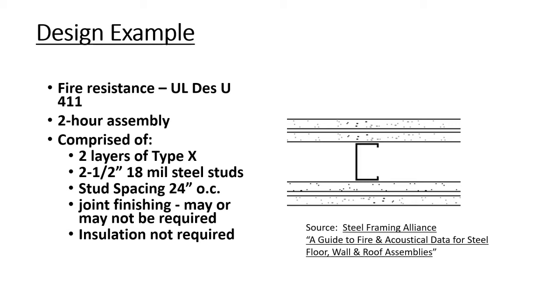Joint finishing for this particular design, that is the joints between the gypsum panels themselves, may or may not be required. This is a very unique situation for fire resistance testing, but in this case, because it also has to have an acoustical rating, the joints must be finished. Also, for fire resistance in this particular assembly, insulation in the stud cavity is not required. With these materials and in this installation, we have now met the requirements for fire resistance.